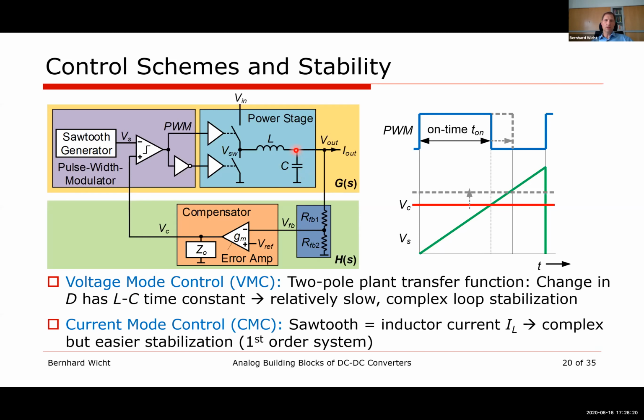But the common practice to get a low ripple is to add a linear regulator after the switch mode regulator, which basically sees only a little voltage drop of a few hundred millivolts across, so that it also doesn't degrade the efficiency that much. But this regulator allows to get very low ripple.